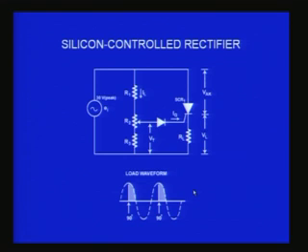So like that you find for every half cycle only a portion of the half cycle is delivered across the load. If I reduce the current, I can make it switch on here or here. That means at any angle between 0 to 90 degrees I can switch the SCR on, but I cannot go beyond 90. When I want to go beyond 90, there is a corresponding point below 90, and therefore the SCR will trigger here itself, and it will not wait for the later point when the gate current is available. And therefore if I want to control more than 90 degrees, then I should not use a DC like this, but I should use a pulse.